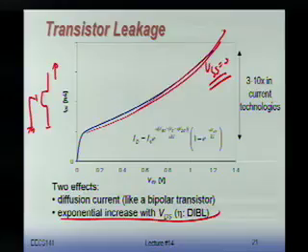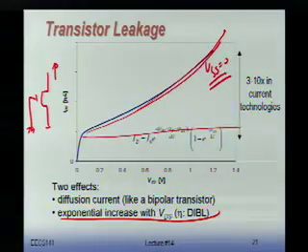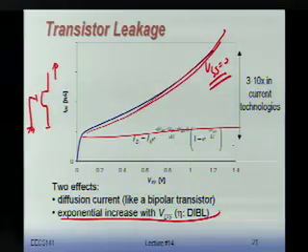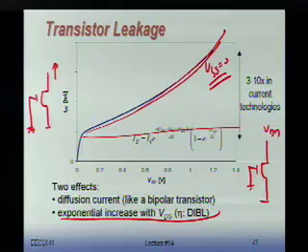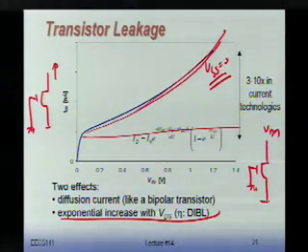And it's kind of annoying, right? If you look at current technologies, going, let's say, between 0 volt and 1.4 volt, or approximately, your leakage current might go up by a factor of 10. So it's a really bad idea to have a transistor like this. This is really not good, because it maximizes the leakage, which is what we would have in a normal inverter anyhow. Okay? So be aware of that.